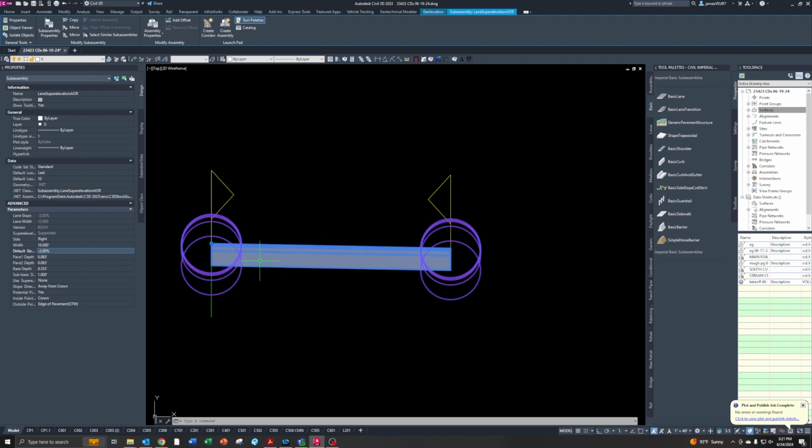Sometimes they'll have the pavement section separate, but that varies from jurisdiction to jurisdiction. But you're going to match the pavement depths based on what that pavement section says for the different layers of the pavement. So this one was 1.5 inches of type E coating.